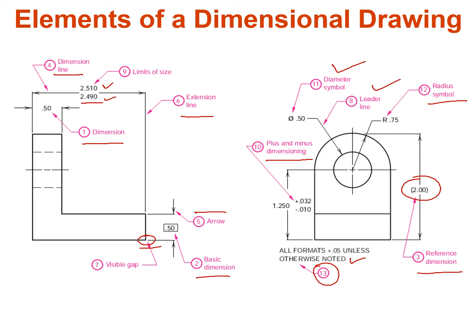Actually, the machines that we use for manufacturing are not that perfect to manufacture an object exactly to the same size. For example, let's say that this is a rectangular block, and the width of that rectangular block is 5 inches. Then we do not have such precise machinery to actually manufacture this object exactly to 5 inches. So what we do, we select two limits for this 5 inches. That will be the acceptable range that will be used to actually maintain the width of that object.